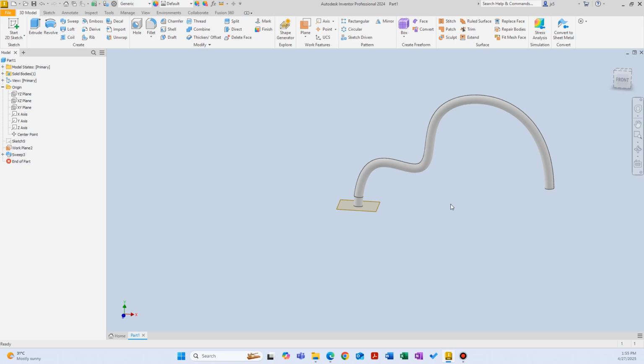If you want to keep your design very realistic, you can use the spline feature to modify it as you please. And of course, you can always go back in the sketch and modify the reference points of the spline and manipulate the design. So these are just quick examples about the sweep feature.